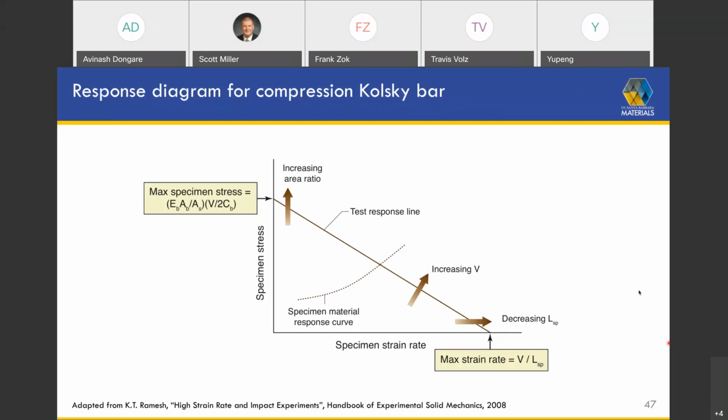Now, depending on whether you're calculating the stress on the back face or the front face of the specimen, you use either the strain in the transmission bar or the two strains in the incident bar, being the incident strain and the reflected strain. Okay? So we know we can measure those forces accurately.